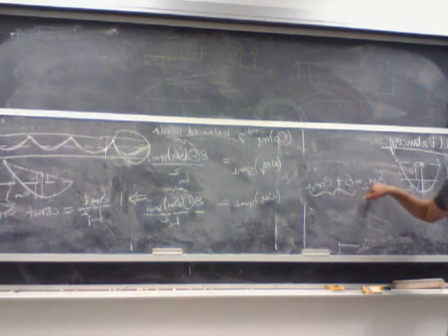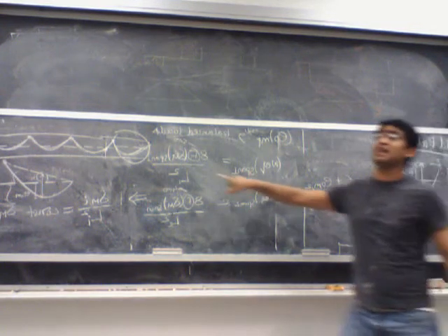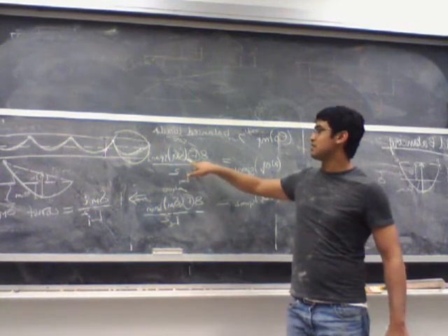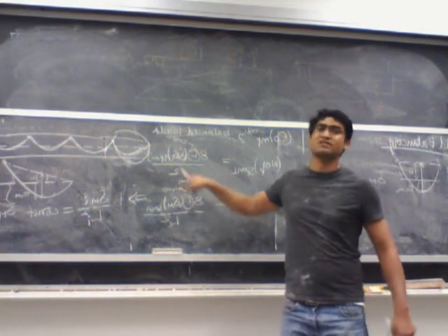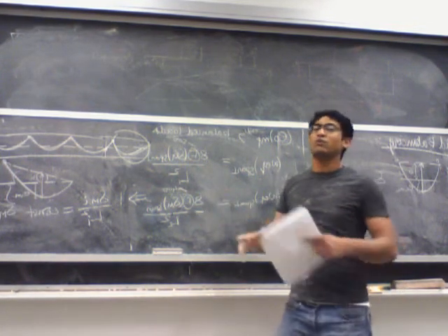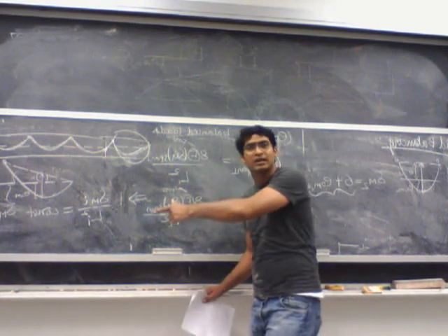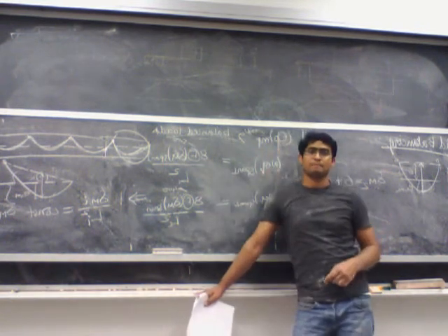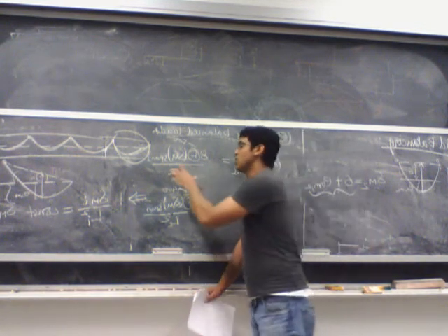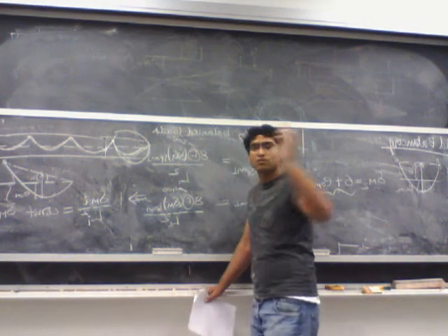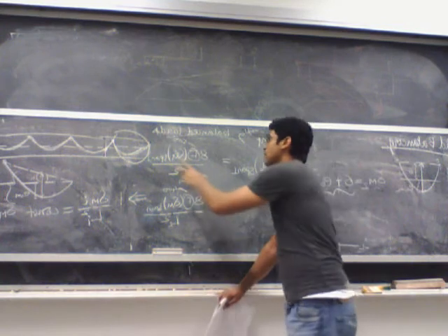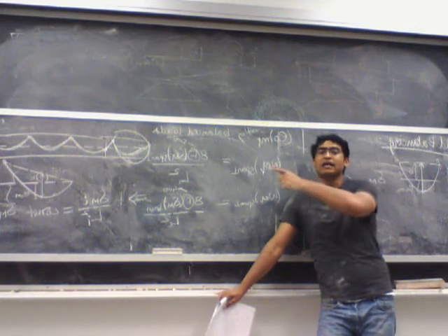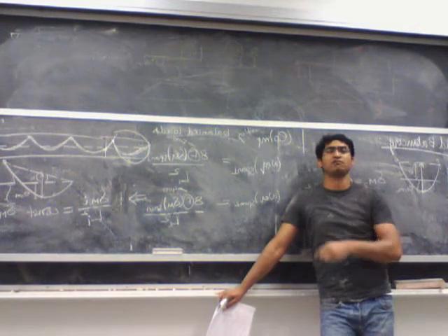So I actually have to make delta M to be constant if your span length is constant. If your span length is not constant, then you are actually equating delta M over L to be the same for both the spans. So that's what I'm trying to say is maximize both the delta M's. You actually find out the value of F and pick the maximum F. So that automatically takes care of the fact that if you have a different length for different span, it is already accounted for when you are actually calculating the value of F. You can directly equate the delta M's if your span lengths are the same, which was the case in the assignment.